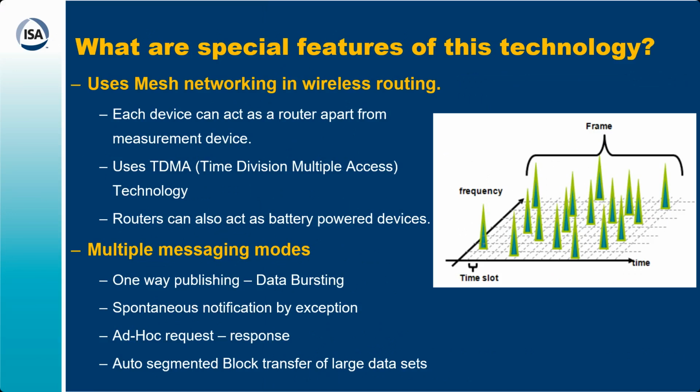It has different modes of communication like one-way publishing and data bursting, and spontaneous notification when an alarm comes, if any problem comes, it gives you the spontaneous notification. Plus, the network manager can also send an ad hoc request and you get a response on some specific packages. Plus, it also has the special feature of auto segmented block transfer.